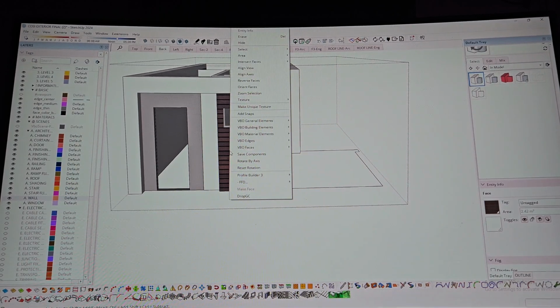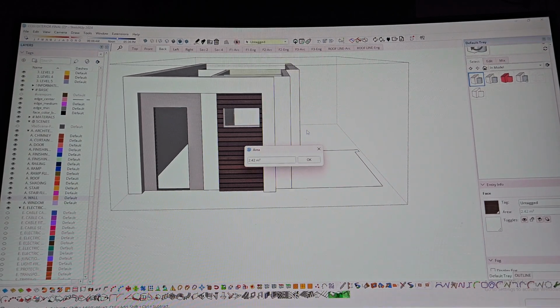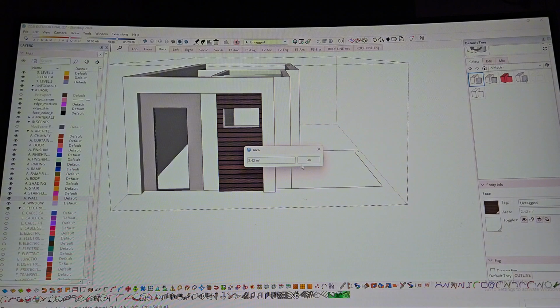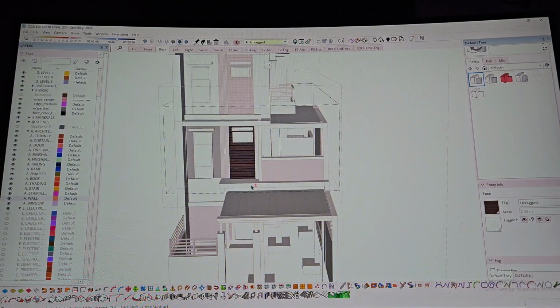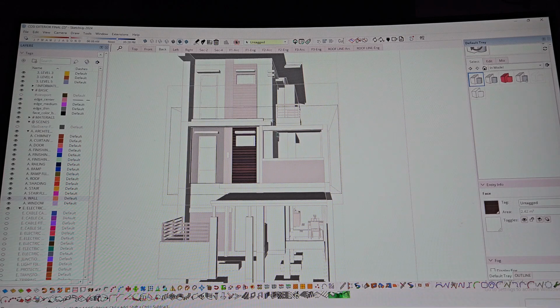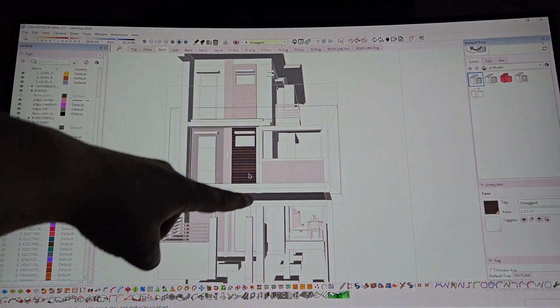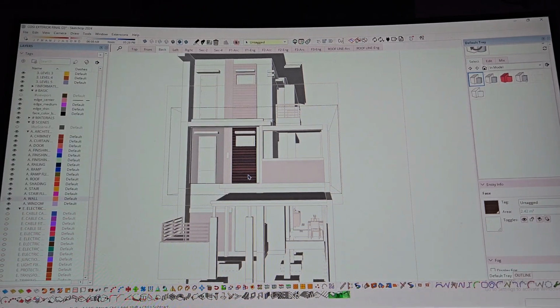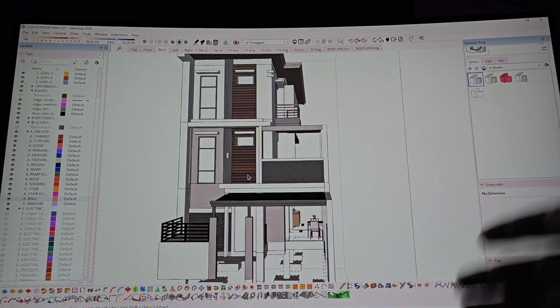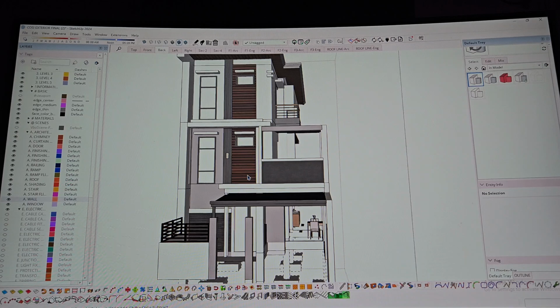I could also do right click area, material, or selection, 2.42 meters. If I click the whole thing and then I click all materials, then I know that all my Hardie planks are 5.84 square meters. Then I know how much I should purchase.